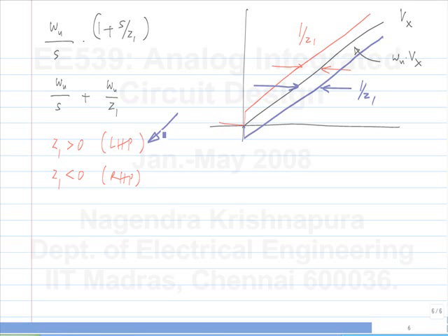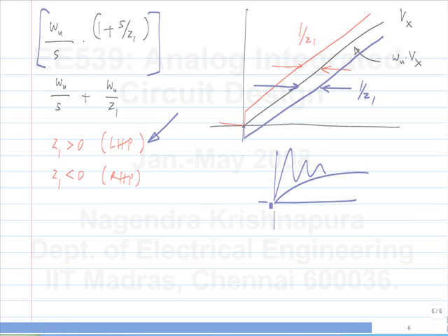Is it okay? Ringing? No, I'll show you what the effect is. So actually the exact response depends on the order of the system and so on. You have just this one, it's still a first order system, so you will not see ringing. You will either see something that is stable or something that is not stable. You'll only see exponential types of responses, right? So only if you have multiple poles and complex conjugate poles will you see ringing. What I normally call ringing is something like this. If I have something like this, I would not call it ringing. This is unstable, but it's not ringing.